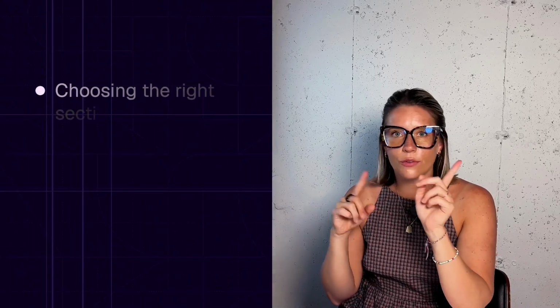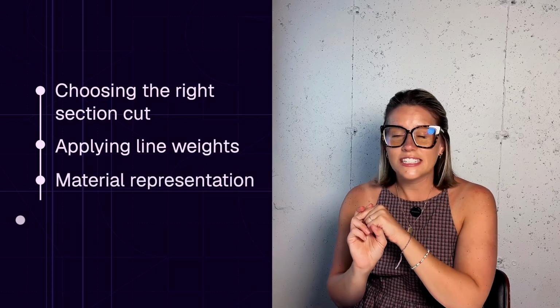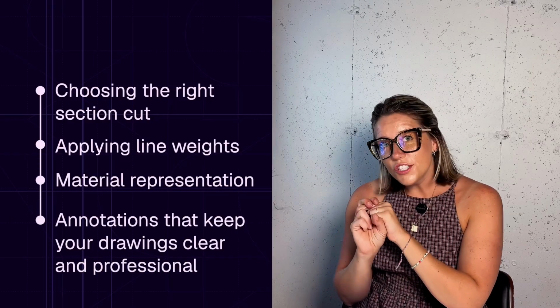And that wraps things up for lesson 5. Today we covered the essentials of creating drawing sections and elevations more efficiently, all the way from choosing the right section cut to applying line weights, material representation, and annotations to keep your drawings clear and professional. You also got a chance to see how Rayon's wall tool, style presets, and side view block library can speed up your workflow dramatically. By now, you should feel confident creating clean, consistent elevations and sections that are both presentation ready and build ready without wasting hours redrawing and reformatting.